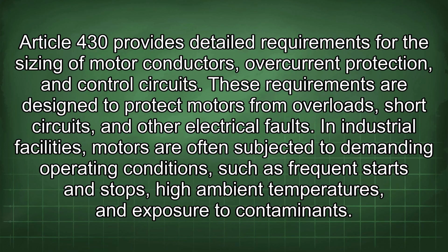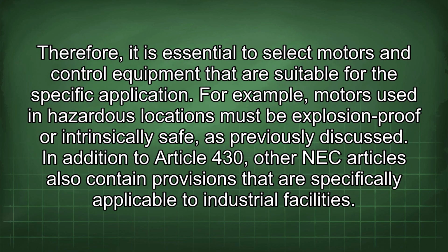In industrial facilities, motors are often subjected to demanding operating conditions, such as frequent starts and stops, high ambient temperatures, and exposure to contaminants. Therefore, it is essential to select motors and control equipment that are suitable for the specific application. For example, motors used in hazardous locations must be explosion-proof or intrinsically safe, as previously discussed.